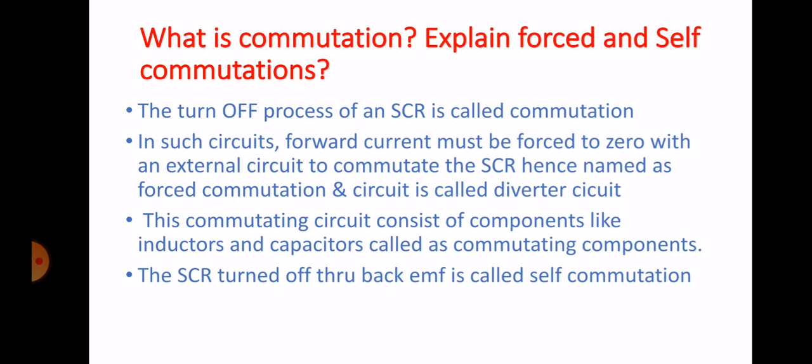And self commutation: the SCR turned off through the back EMF of the motor is called self commutation. If the motor reaches a certain speed or RPM, then it induces the back EMF. Through that back EMF, if the SCRs are turned off automatically, this is called self commutation.